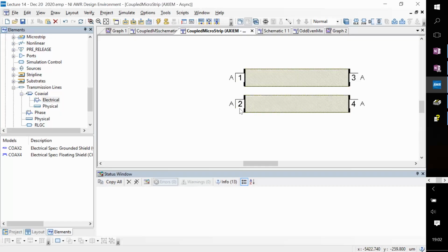and then you put your measurement meter here. So that way it's like a little tap, a small voltage divider kind of thing, which doesn't affect the main signal so much, but you then get a reference. But you know that this power is only 1% of the total power. So you multiply that by a factor of 100 to get a sense for the true power flowing through this. And that is one application of this.